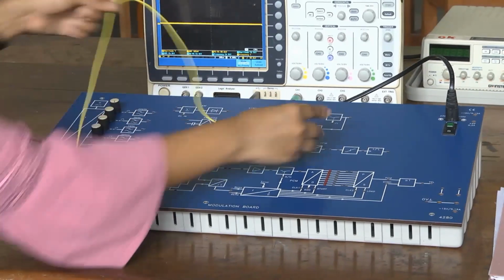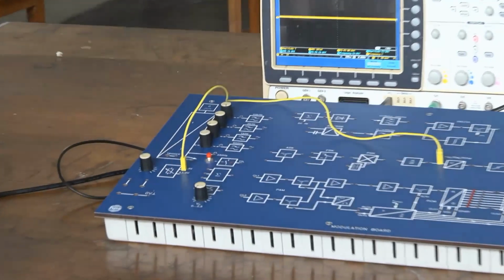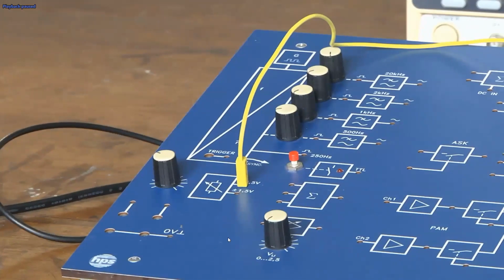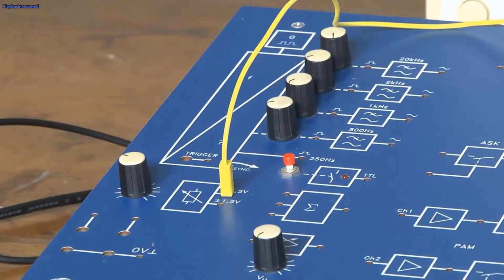So I am giving the input to the circuit, and you can see here, this is as in your lab sheet. We are taking the input from the 2.5 volt plus and minus. Between that range we can give DC voltage levels to our circuit, and from this knob we can change the voltage level. So by using this knob we can change the voltage and see what the output frequency is.